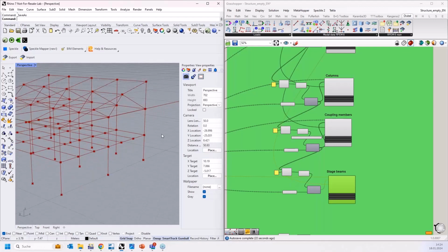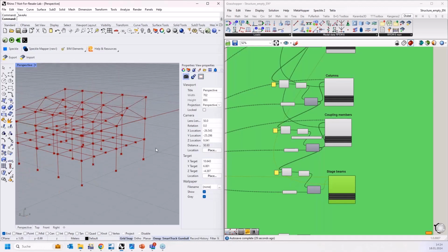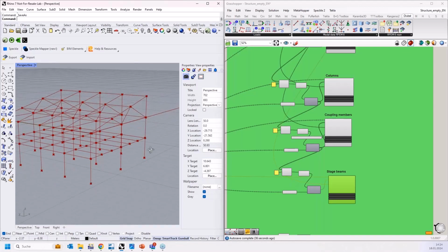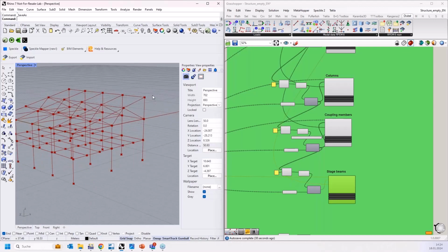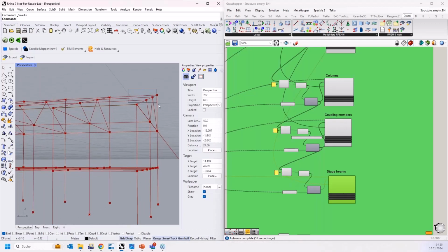What could be an example? Maybe for the columns. It's quite common to assign set of members for columns because it allows you to easier apply loads on it or imperfections. For example, you might want to apply an inclination imperfection onto your columns, and then you have to do it for all at once and not for each member individually. So that's one reason why you may need a set of member. Or let's say you want to apply a load, or even for the design afterwards.